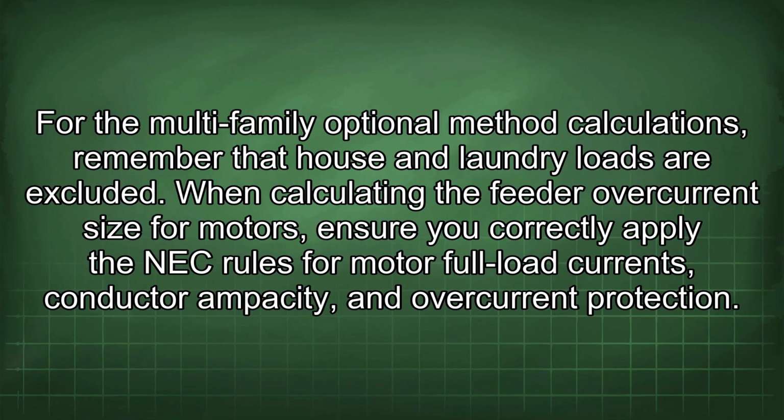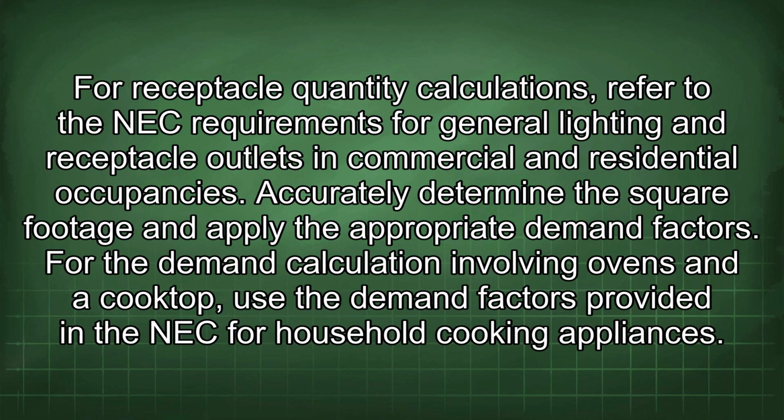When calculating the feeder overcurrent size for motors, ensure you correctly apply the NEC rules for motor full load currents, conductor ampacity, and overcurrent protection. For receptacle quantity calculations, refer to the NEC requirements for general lighting and receptacle outlets in commercial and residential occupancies. Accurately determine the square footage and apply the appropriate demand factors.